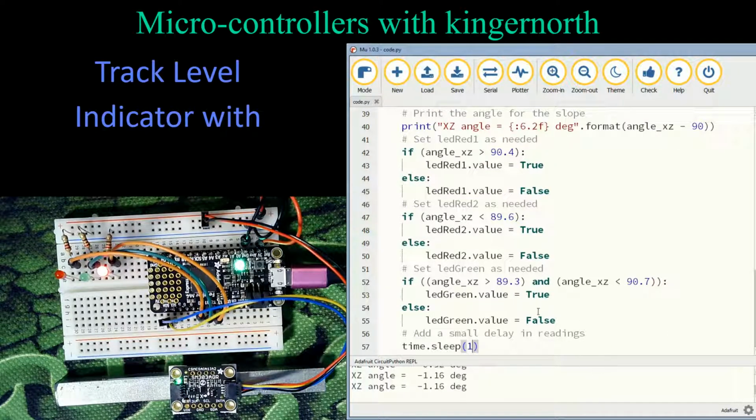Now I wanted to talk about correction, and I can do a correction electronically. I can see by default when I'm sitting there, I'm actually sitting about 1.2, 1.3 degrees out of whack, pretty close to 1.67, 1.17, 1.4, 1.6, just the normal vibration of things going on. So it's closer to probably somewhere in the middle there at 1.2. But it's negative 1.2 degrees. So what I need to do is add 1.2 degrees to angle XZ. I need to add that.